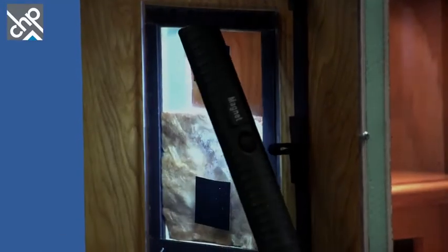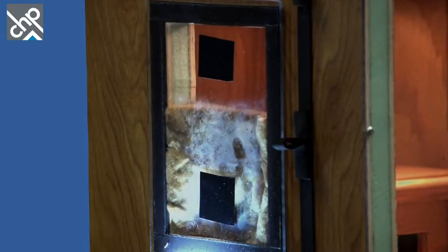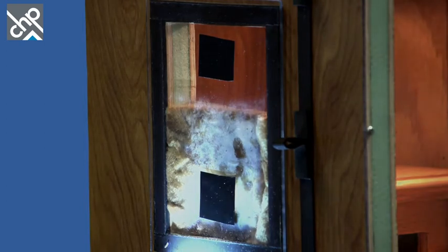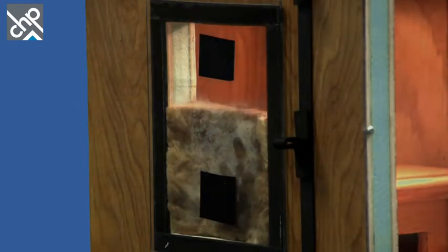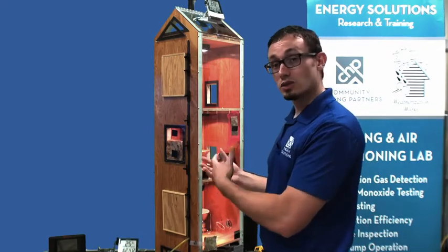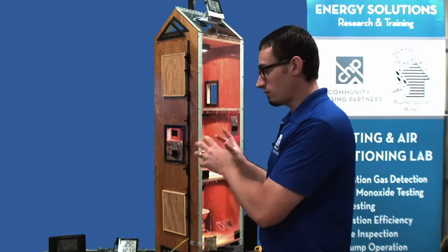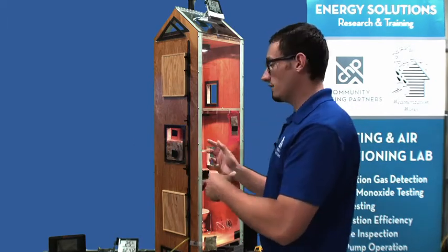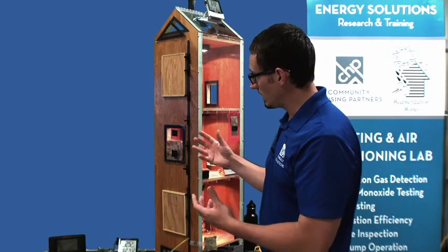So you might be wondering, well, how is that possible? How do you have condensation occurring on that surface? You've got fiberglass there, right? That fiberglass should be doing something, right? Well, if you guys have ever really thought about it, fiberglass in this application is more like filter glass. It's not going to stop airflow. So what we have now is this air pressure, this vapor pressure, this want of the moisture to escape via the path of least resistance if it can.